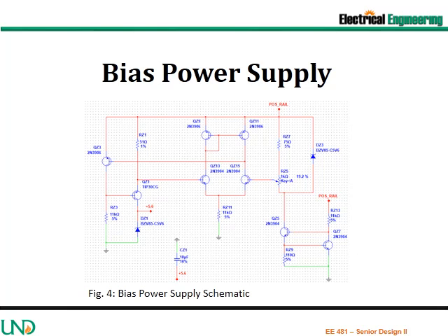This allows a constant current, nearly independent of supply voltage, to be sent to the photodiode bias Zener DZ1. The selected operating point has a Zener impedance of 4 ohms. As a final note, in the final design, RZ11 was changed to a 1.1 kiloohm resistor to raise the bias current of the differential amplifier.